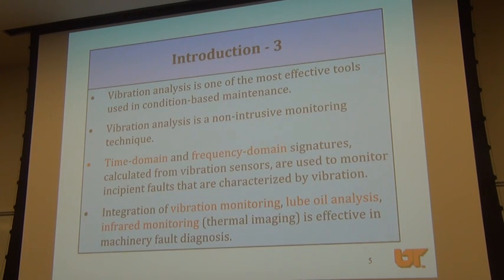You can also have vibration if you have a motor and the bearing is not supported properly, you have loose bolts, then when the rotor rotates, the bearing support is going to shake a little bit. So that can cause vibration. And there are other causes of vibration. We'll get into those.